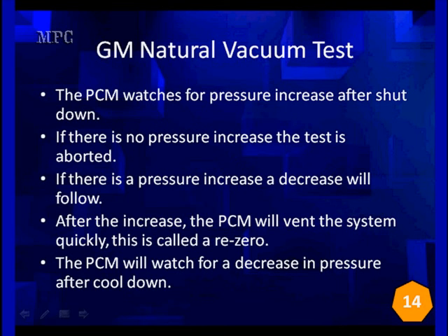The PCM watches pressure increase after shutdown. If there's no pressure increase, the test is aborted. It'll wait and do it again. It's going to keep track of this and eventually do a weak vacuum test if it cannot see a pressure build.